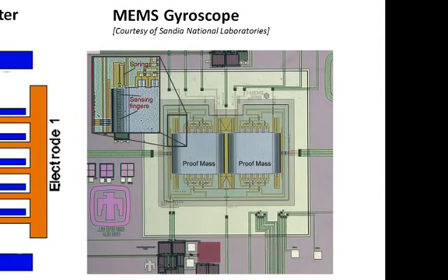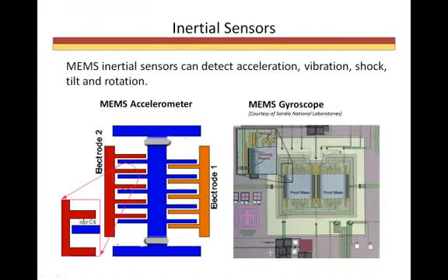This is a MEMS vibrating gyroscope, which is used to determine orientation of an object. This gyroscope uses the physical principle that a vibrating object tends to keep vibrating in the same plane as its support rotates. As the plane of oscillation rotates, the vibrating gyroscope's transducer is affected due to the Coriolis effect, which is the tendency for any moving body on or above the Earth's surface to drift sideways from its course because of the Earth's rotation.